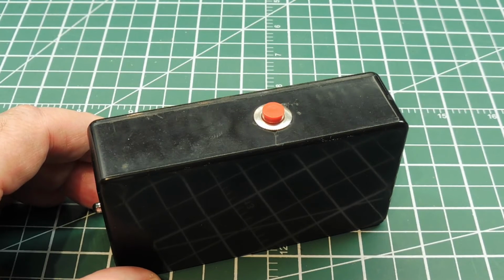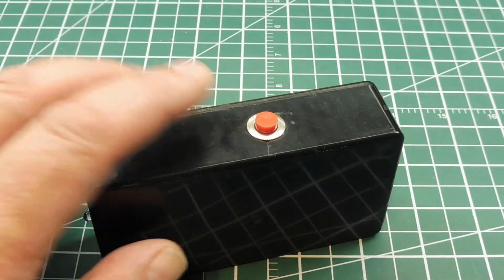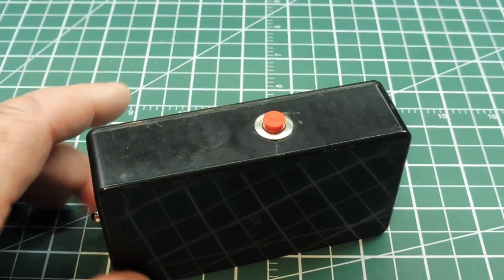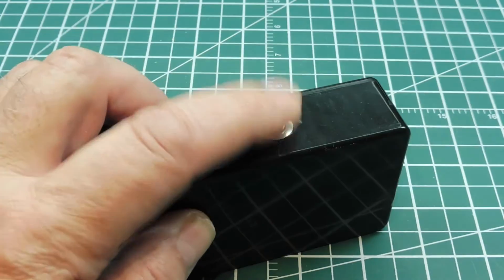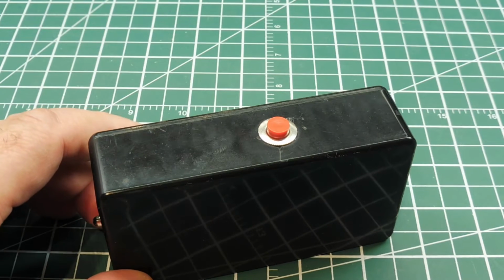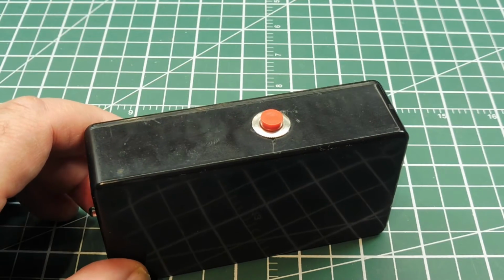Okay, in this video we're going to look at contact bounce, and that's in reference to mechanical electrical switches. Now here you see a little push button switch mounted on this box. That's a little human interface into a microcontroller, usually through one of the GPIO lines. It could indicate an on-off condition, or a yes-no decision, or maybe even counting data. The microcontroller expects to see clean signal transitions from the switch, which is not always the case, and that's what we'll look into in this video.